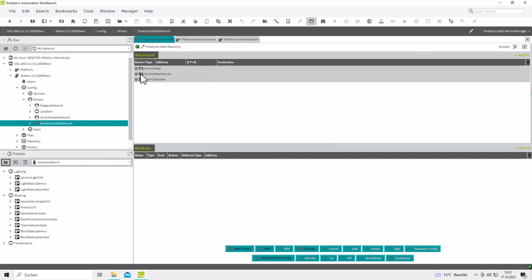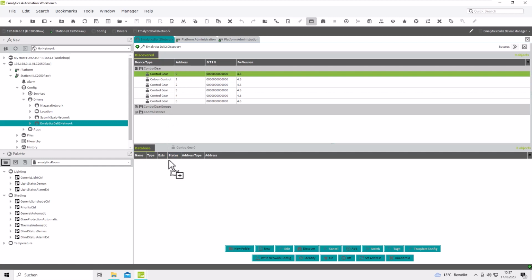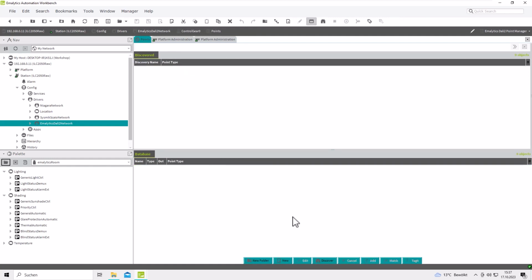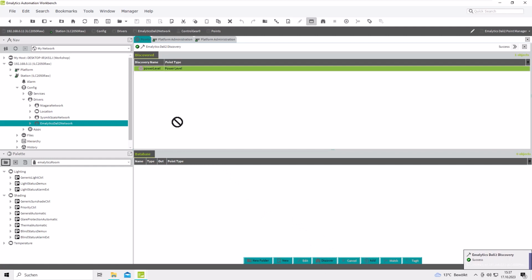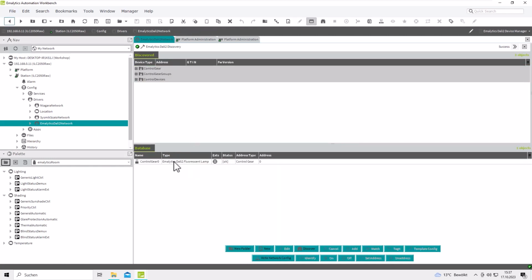Let us have a look at the control gears. The addresses we see here, they are randomly addressed to the devices. If our project only requires broadcast communication, we don't have to do the random addressing, but this will also give us some advantages. Let's say we just have the random addresses, implement them here. We just have the devices now implemented in our system. As long as we do not implement the single data points into this device, we just leave it free. We don't have any license data points used, but we see if a communication is broken to an end device.